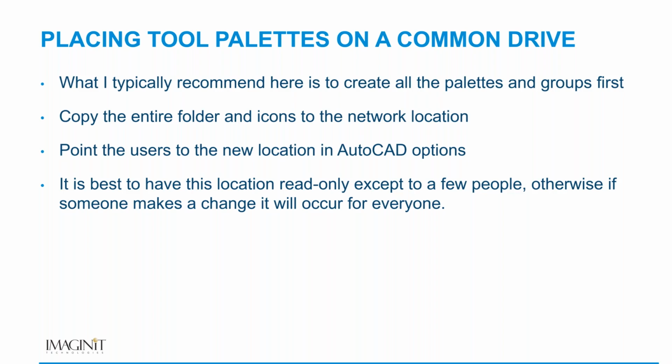Sean, that's more of a CAD standards question, but what I would normally recommend in that case is that you copy your tool palettes to the local C drive. You have your working copy on the network drive. You copy that locally via sync for the people who need those tool palettes, and then you sync everyone locally to their C drive. And that is what I usually recommend in those cases. Especially a lot of us that have remote users, that is going to be the biggest thing that you need to think about, is going that route.